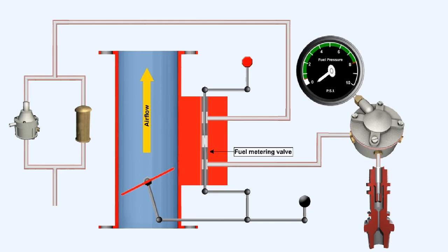The second of the two valves which control the fuel flow into the engine, the fuel metering valve, is mechanically connected to the throttle butterfly. It controls the flow of fuel coming from the mixture control valve according to the position of the throttle butterfly. Thus, fuel flow to the manifold valve, and subsequently the injectors, is proportioned to airflow.